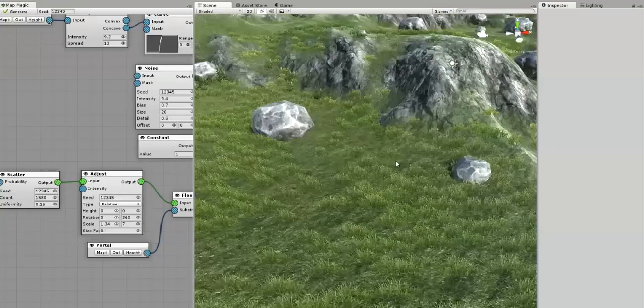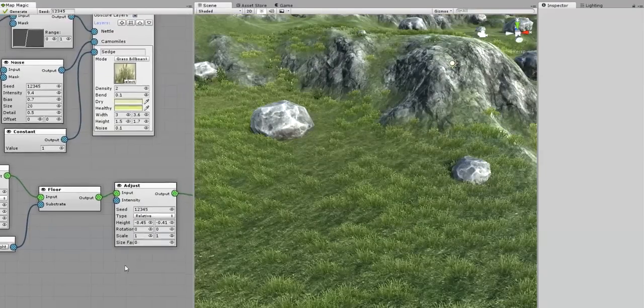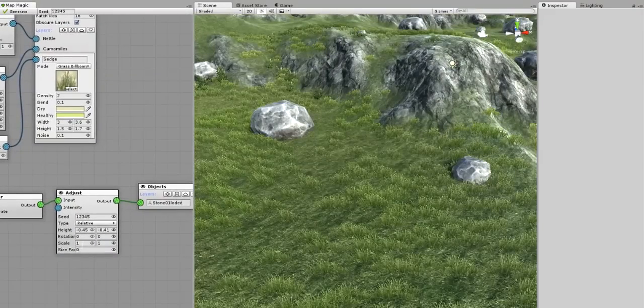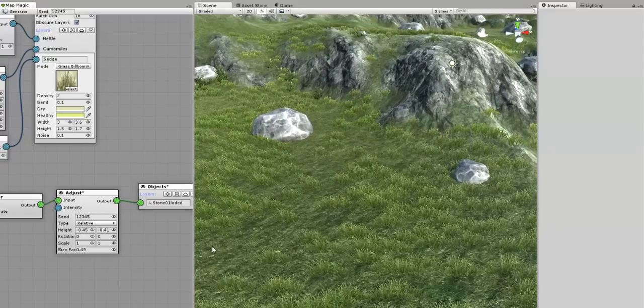When the scale factor is set to 0, the object size is not taken into account. All of the stones are lowered at the same height, both about 40 centimeters. But when I start to increase the factor, this 40 centimeter height is multiplied by the size of each stone. So at scale factor of 1, both of the stones are plunged at the same level of their mesh.